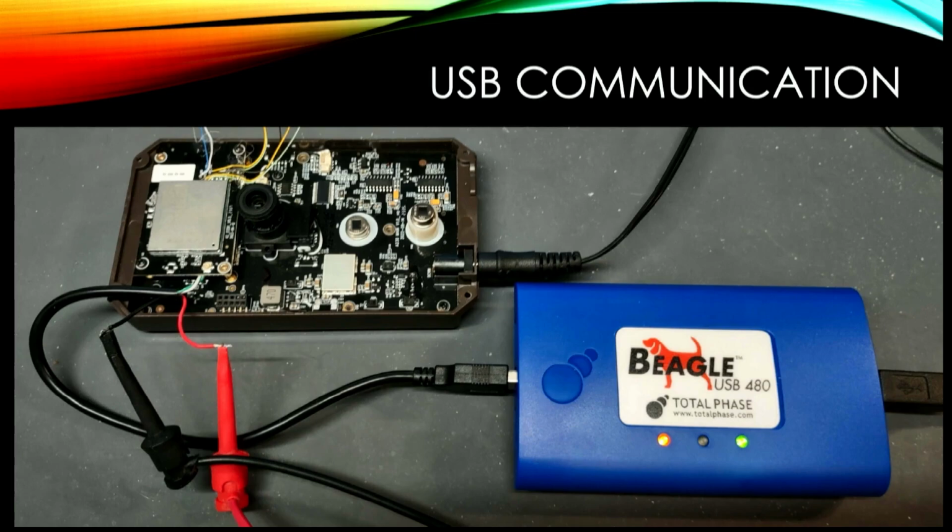In this particular case, you see these devices. Sorry, I'm going to get in here. You see this hooked up right here. It turns out for the USB sniffer to work, it basically has to detect VBUS. Normally on USB cables, you have ground, you have VBUS at 5 volts, and then you have D minus and D plus, which are the data lines. When you look at the chips, VBUS is never brought to the surface. It's underneath the chip, so most of the time you can't even tap into it. Not easily. I may mention another method here in a little bit to potentially get access to it.